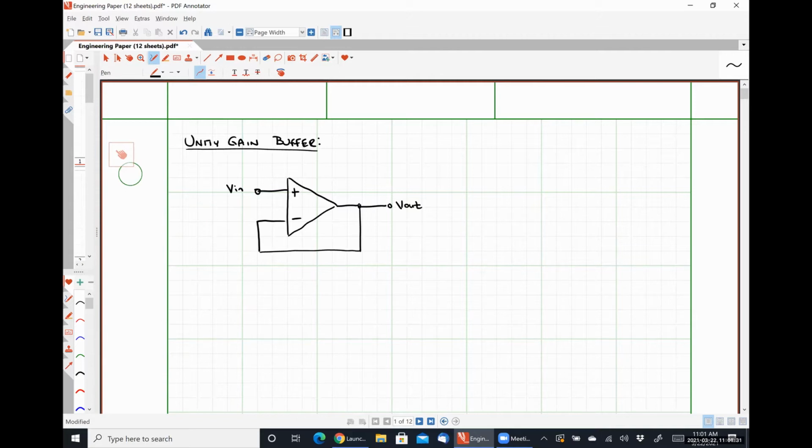All of the examples that I'm going to work today are negative feedback amplifiers, so we're going to be using the ideal op amp rules in order to analyze them and develop their relationships. Also, we are going to assume that all of the amplifiers have sufficient values for VCC plus and VCC minus that they would operate. So all of these are on and working within the linear range is the assumption that we're going to make here.